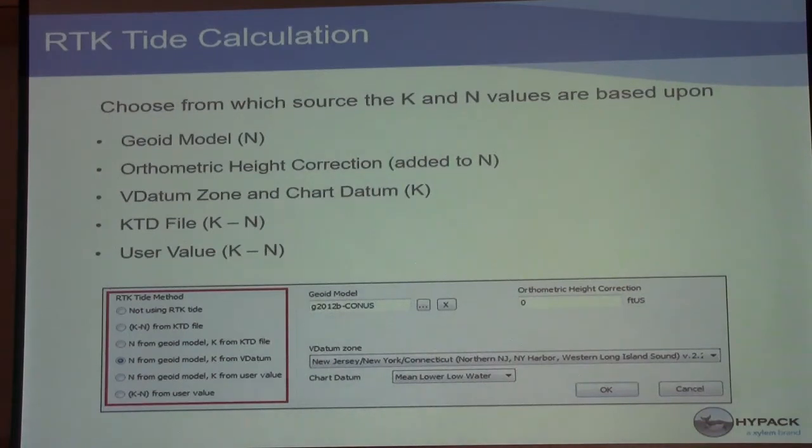So typically, again, in HYPACK, you're making the assumption that you're working in RTK. The GPS is in WGS84. You're outputting ellipsoid, antenna height above ellipsoid. Okay, and then we're doing all the other conversions. There's a lot of support calls where they might enter... I guess you have the ability in a lot of GPSs to output a local height. If that's the case, you're going to load a geoid model or KDD file and so on. So there's a lot of stuff like that too.